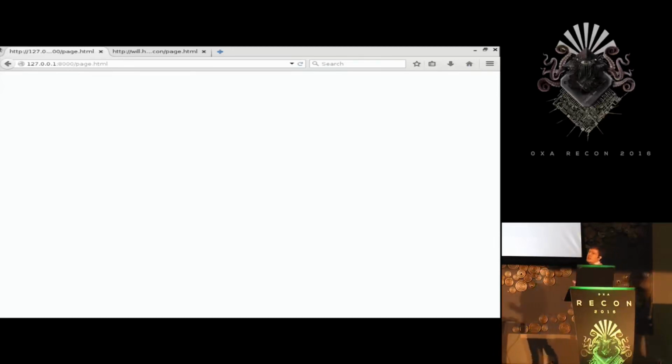Remember, we can cheat. In the loadable processor module app note that they had for this particular firmware file, it had a number of memory locations, and those memory locations were used to configure the address matching. So you knew that those memory locations would contain an address. And therefore, those addresses or memory locations had to be loaded somewhere inside this so that they could be used. So we can go constant hunting, go hunting for the binary value of the constants of those memory locations, and that's an immediate, real quick jump to move immediate, followed by move register indirect, and you find those right away.